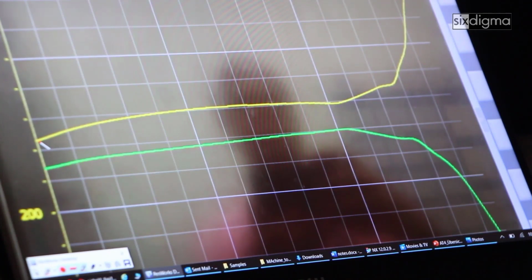Whenever you see this graph going up, the table is rotating clockwise. If you see it going down, the table rotates counterclockwise. Here, we are machining the concave side of the blade. As we get closer to the leading edge, there is a small area where the axis reverses to a counterclockwise direction before it proceeds with its clockwise movement.